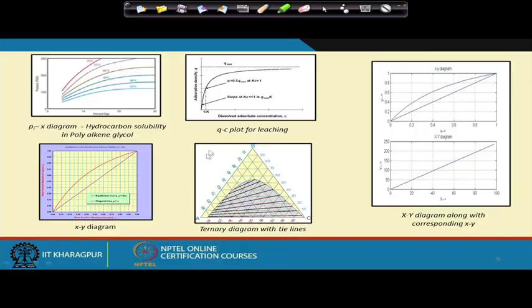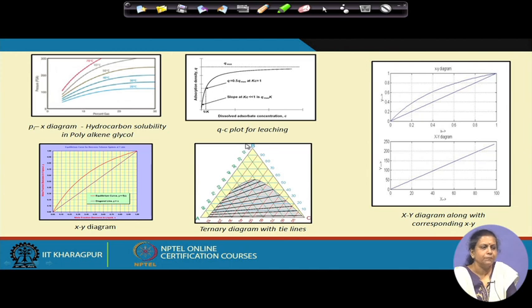We bring B to it such that it extracts C from A. Now, C dissolves in A, C dissolves in B, and even if A and B have very little mutual solubility, there will be some amount of solubility between A and B. Therefore, there has to be equilibrium between AC, BC and AB. In order to show all this equilibrium in a single curve, usually we take the help of a ternary equilibrium plot, which I will be explaining after I discuss the other parts.